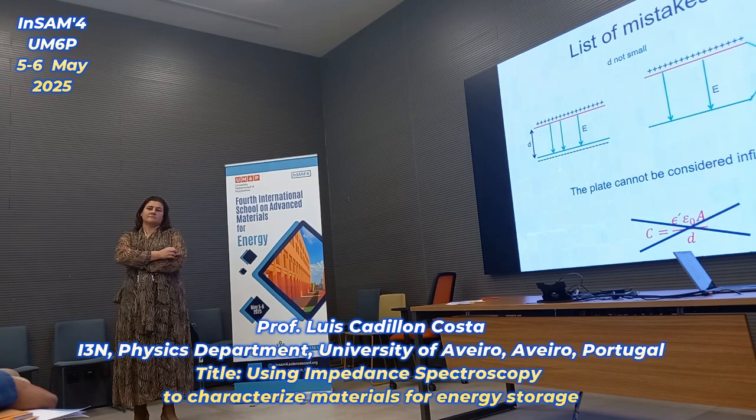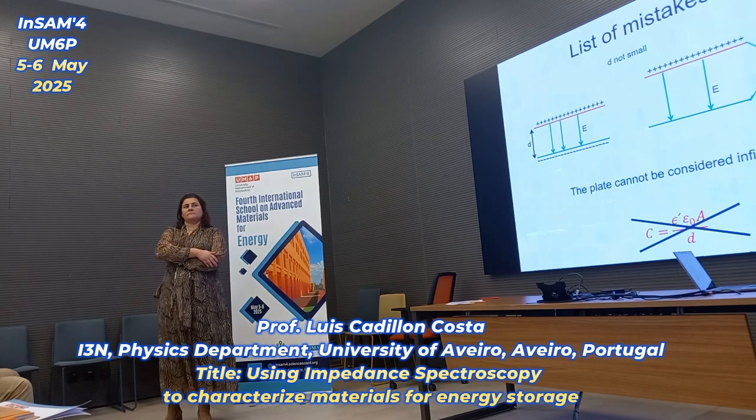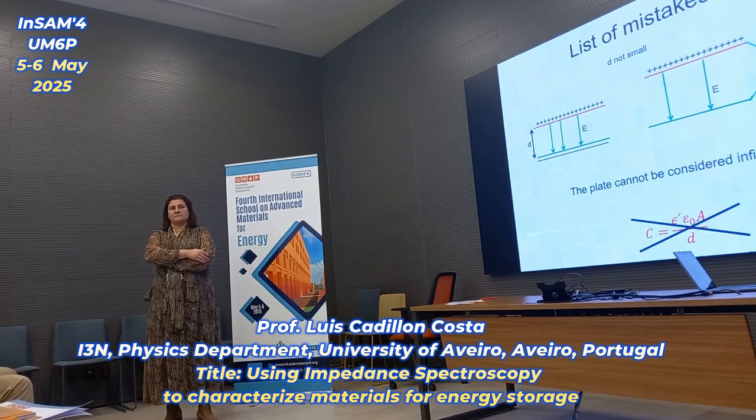If I want to make a measurement along some other axis, I put my material here and I rotate. Rotate the waveguide? No, I rotate the material. I have the electric field always like this. My material is anisotropic. I make a measurement here and I calculate epsilon prime, epsilon double prime, and then I change by 90 degrees and I calculate epsilon prime, epsilon double prime again. And if it is anisotropic, it is absolutely different.